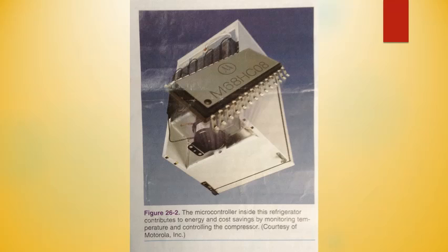The microcontroller is also dependable. Integrated circuits such as the microcontroller are much more dependable than relays. Before, control circuitry relied on many electromechanical relays and timers to control the system. Relays depend on electromagnets to move armatures and contact parts, so they eventually wear out due to mechanical friction. Relays are also susceptible to damage caused by dust, dirt, corrosion, rust, insects, and other contaminants that can interfere with the moving parts. Microcontrollers, on the other hand, have no moving parts. This provides a much higher rate of reliability.